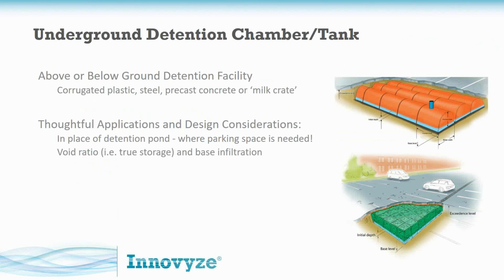A couple of items to consider when designing: what's the real void ratio, and what's the infiltration beneath that facility? You might have some in situ soil where even an inch or two an hour can really reduce the volume that facility needs to hold on to. Like all of these, you need a real hydraulic assessment of how this facility will be put together. Where the orifice is, where items daylight down into these tanks, those matter.